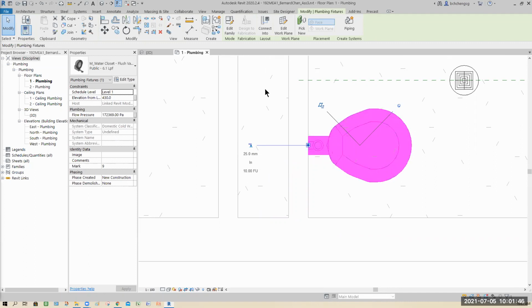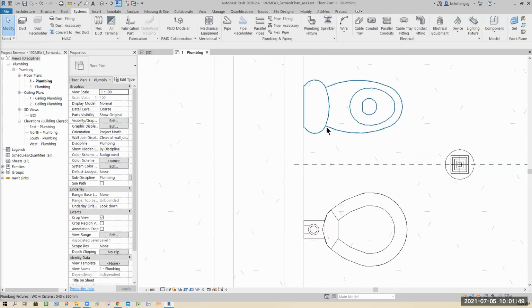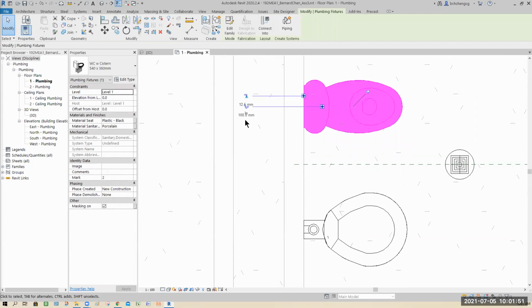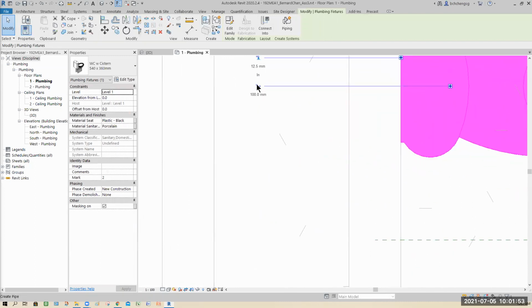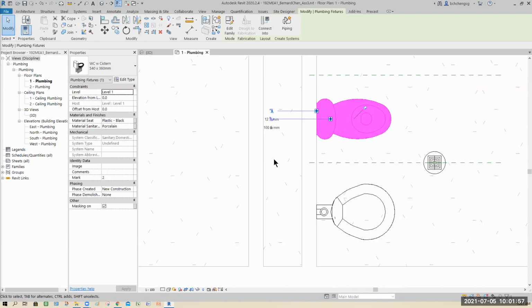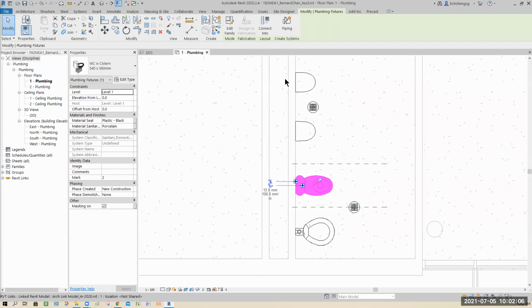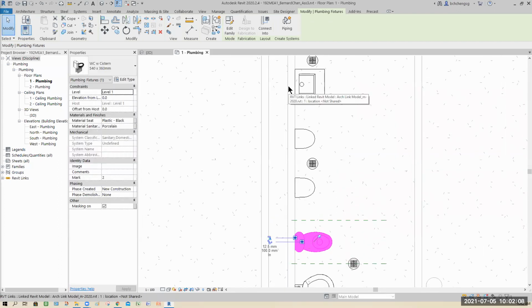Actually, there's an overlap. They should have 2 values. See this one? Sanitary is 100. So in other words, your pipe size here is minimum 100. For fluid like urine and wastewater, a 100 mm pipe is not a problem.